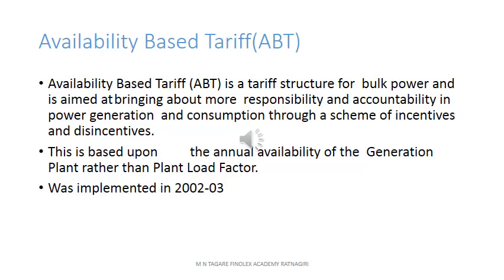In this, the annual availability of the generating plant, rather than the plant load factor, is taken into account. That means how much load is on the plant is not considered. Whenever there is a need, whether that plant is available for generation or not, this fact is taken into account while doing the calculation. So this is the introduction of availability based tariff.